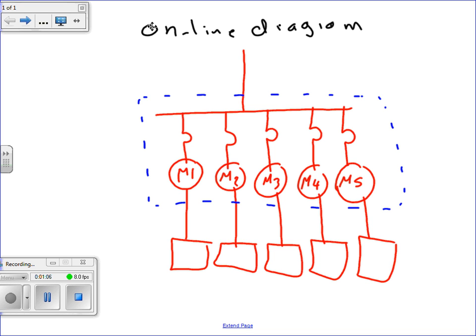Okay. So the one-line diagram is basically the skeleton that puts the whole electrical system together, from coming from the Xcel Energy, the electrical utility, into distributing the power directly to the system. So what you're looking at is a box like this. Inside this box, I'm just going to say 500 amp.